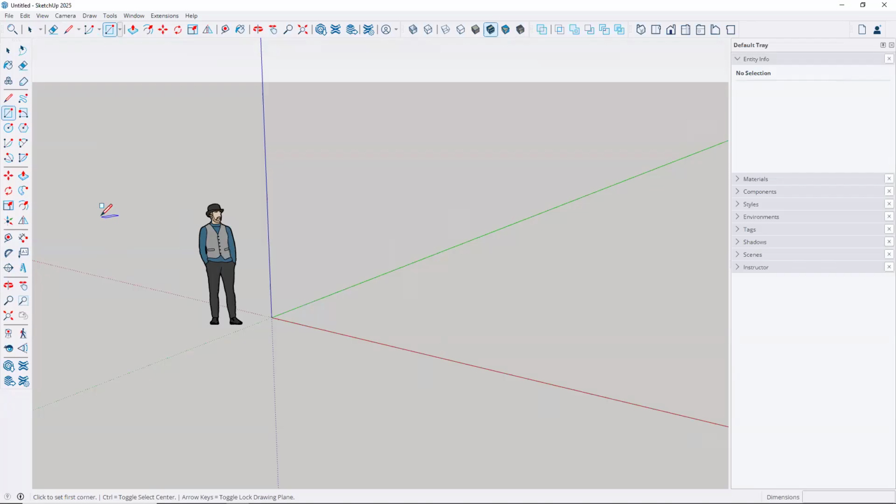You'll just go ahead and type in dimensions and it will take the dimensions. So for example, if I click on line here for a second and I just give one click, you'll notice where it says length. And I can actually type a length, an exact length, let's say 3 feet for now. And I'm not moving my cursor. I'm just typing 3. And notice how the length changes. And I want that to be 3 feet. And then I enter and it will draw a line that's 3 feet in length.